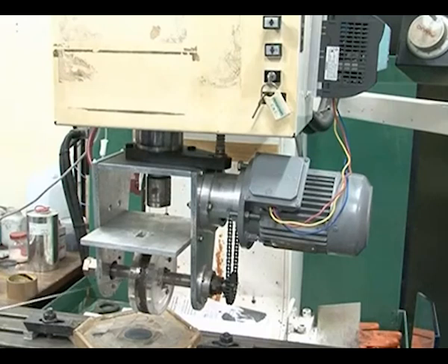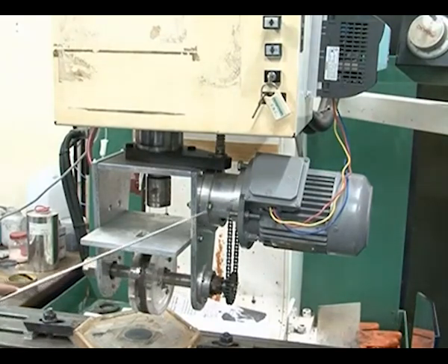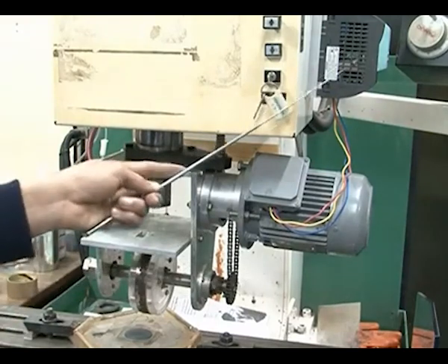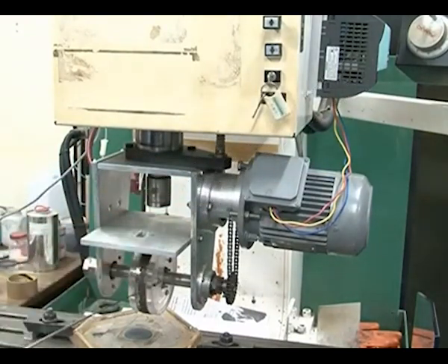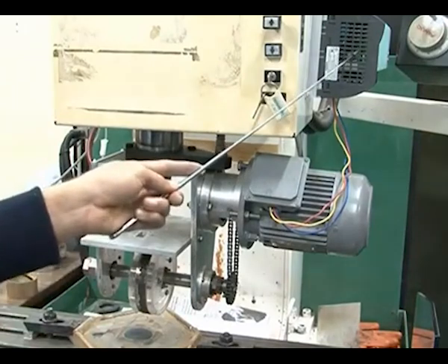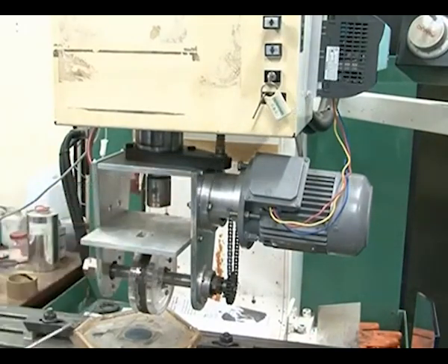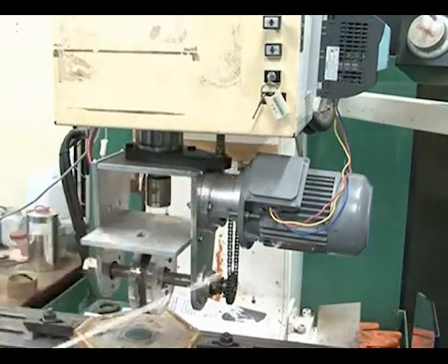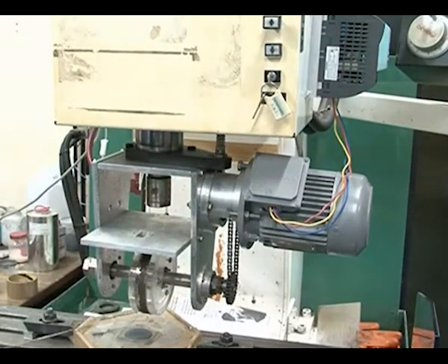This is a permanent magnet which is covered by two perspex sheets, and this whole assembly is called the carrier wheel. The carrier wheel is connected to the AC motor through this timing chain, and this AC motor is again connected to the variable frequency drive, so that the wheel speed can be controlled automatically by this variable frequency drive. You can even give a particular value of the wheel speed so that it rotates at that value only. It is also required that most of the components should be non-magnetic, so that the magnetic field lines should not be disturbed by these components.